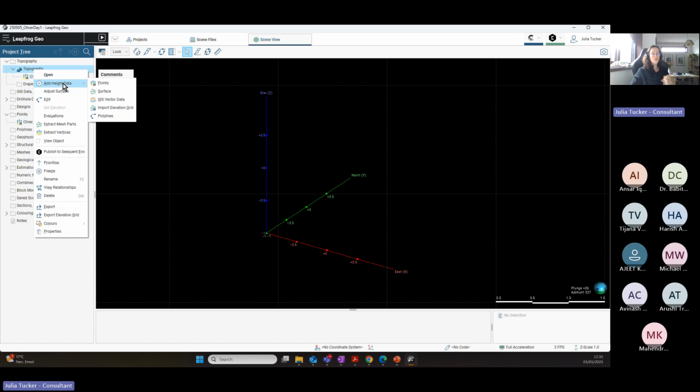This is also going to be useful when we have the colors and the colors are not matching exactly the topography. We can adjust the topography to the colors, or we can adjust the colors to the topography. This depends on how reliable your data is, and you have to have the knowledge of which is the more reliable data: the color of the drill holes, the topography, maybe a third campaign. This depends on your data, but it's possible to do both ways.